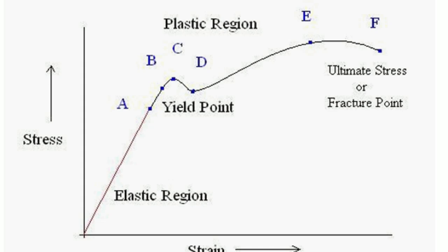So what is this? Point C is the yield point. Up to here is the elastic limit. That means when we remove the load, the material will come back to its own position. After that we increase the load, and at point E it will start breaking, and F is the breaking load or the fracture load, and this point is called the maximum or the ultimate strength.